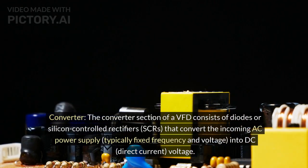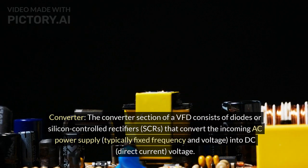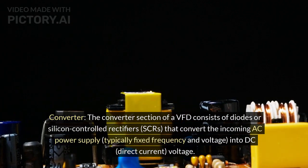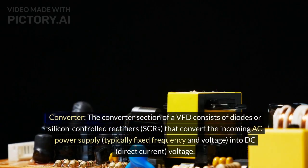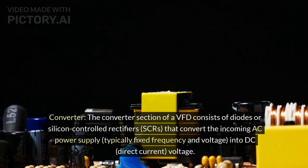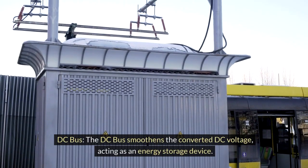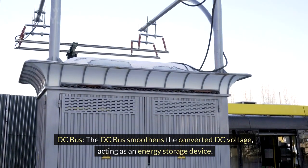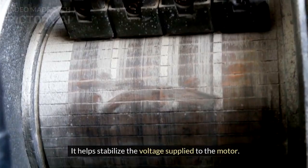Converter. The converter section of a VFD consists of diodes or silicon-controlled rectifiers, SCRs, that convert the incoming AC power supply, typically fixed frequency and voltage, into DC, direct current, voltage. DC bus. The DC bus smoothens the converted DC voltage, acting as an energy storage device. It helps stabilize the voltage supplied to the motor.